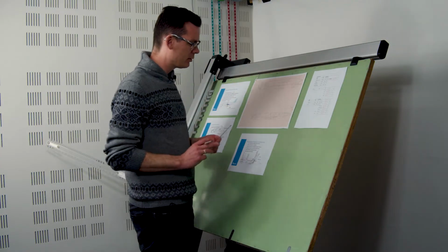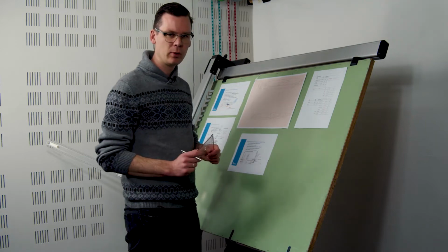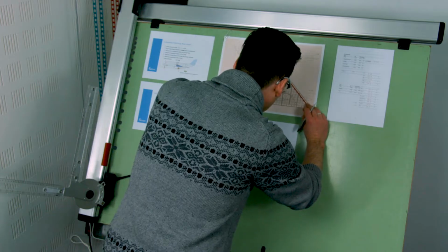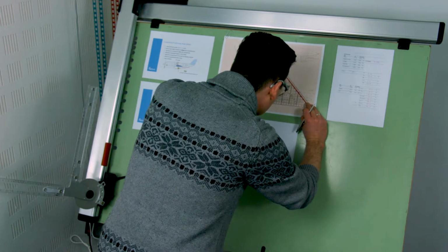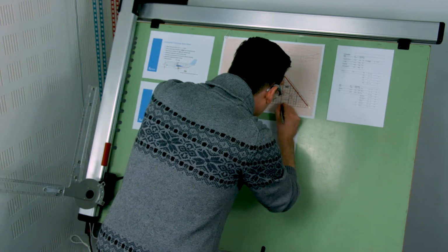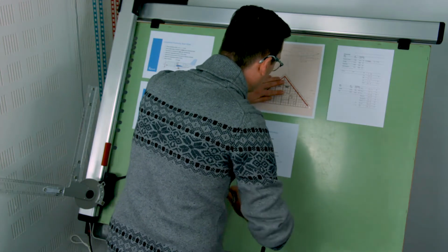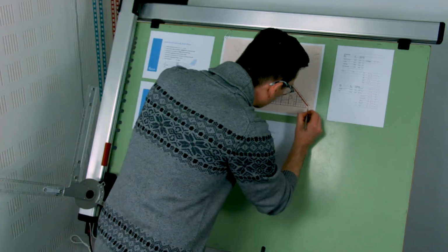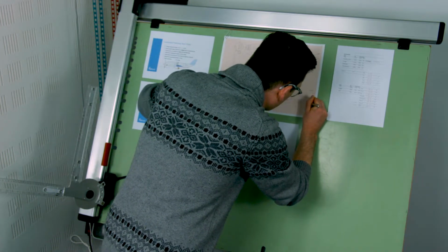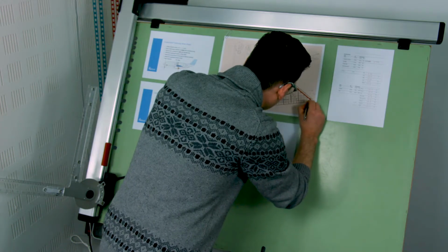So first, let me draw that line. Now I have to draw another line at an angle of 12 degrees. Just to help me out a little bit, I'm making a help line close to the fuselage, because positioning your protractor by hand parallel to 12 degrees is a little bit difficult. I'm constructing this help line that I'm going to get rid of later on.